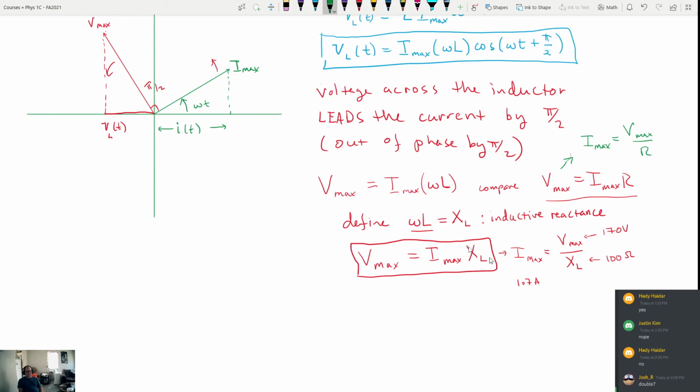So this is this thing that we call reactance, X sub L. It's like a generalized version of resistance because it tells us the effect of putting this inductor into the circuit: the bigger the value of the inductor is, the smaller the output current you're going to get. And the other piece of it is this omega right here. So let's figure out why that's in there. Why does XL depend on omega?